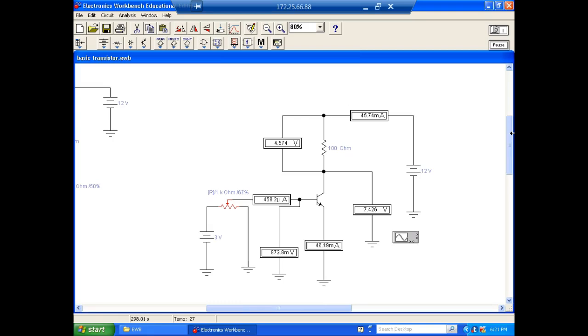How do I know it's in saturation? When this guy right here drops the applied voltage, then I can keep putting base current in and it's not going to do anything. But every time we calculate the gain, it's going to stay around 100. So here we can actually see this. 104, so the gain is about 100 for this transistor.